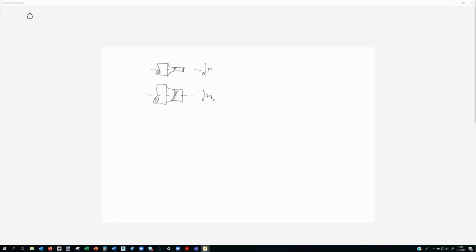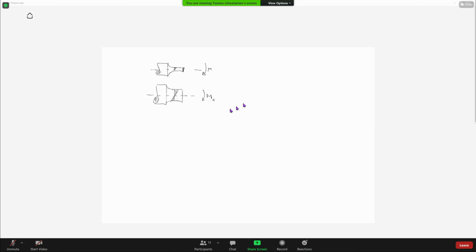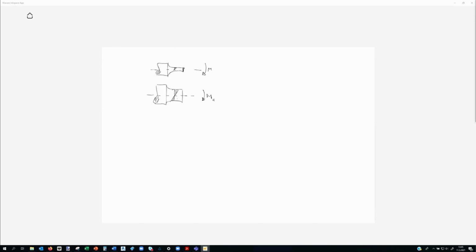And now when this is amplitude, it means that it is pulsating on both sides. So while pulling downwards, we have tension here and compression here, right? But when it's going upwards, it's vice versa. That is causing the amplitude. And now when we have this tensile force, that is causing an evenly distributed stress over there. That is now the base level around which the bending amplitude is fluctuating. So this F is creating the mean stress.